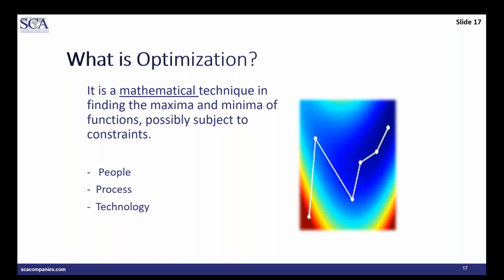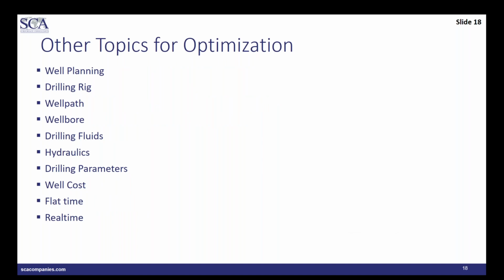Clearly, you can see the difference between these three: performance, efficiency, and optimization. So a lot of things may change. Now, probably we may want to maximize rate of penetration, minimize mechanical specific energy, or minimize the cost. But we have to clearly understand the constraints in which we are dealing with. The optimized parameters like weight on bit, turn rate, RPM, and flow rate are ultimately important, because it dictates the use.